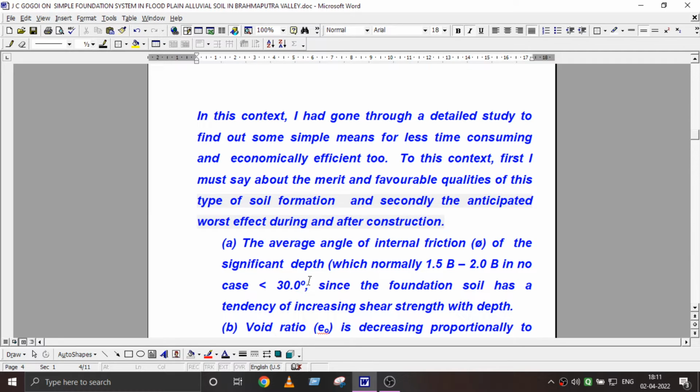However, the slip angle of soil of any kind, whether it is hard clay or plastic clay, is alpha equal to 45 plus or minus phi by 2, yet all scientists and scholars confirm that the shear angle is 30 degrees. Since below the foundation the load distribution angle is 30 degrees, automatically the upper shear failure shall also be 30 degrees.